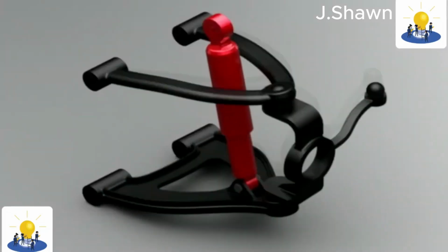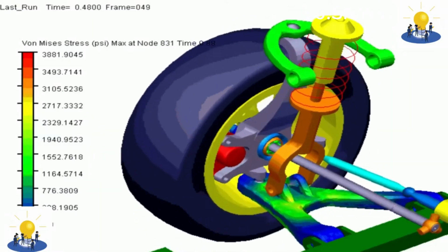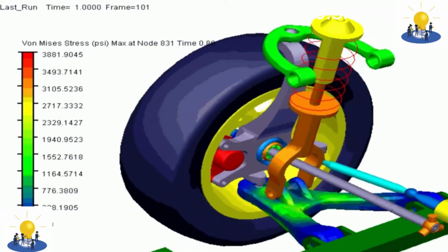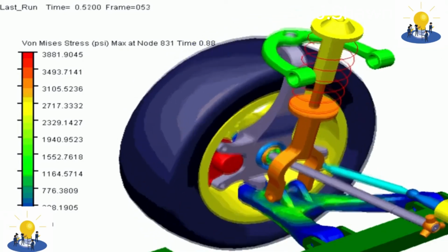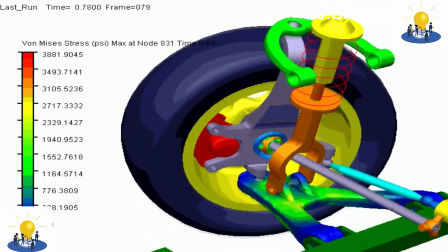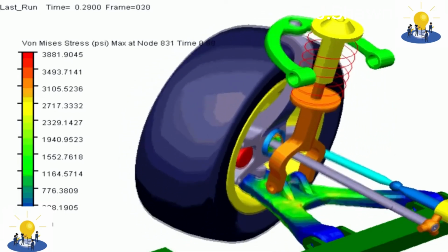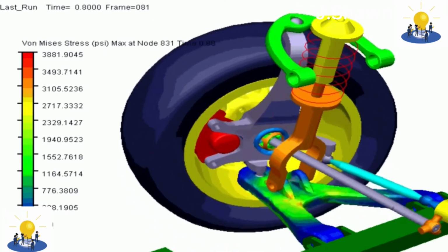In elevation view, the suspension is a 4-bar link, and it is easy to work out the camber gain, C-camber angle, and other parameters for a given set of bushing or ball joint locations. The various bushings or ball joints do not have to be on horizontal axes parallel to the vehicle's center line. If they are set at an angle, then anti-dive and anti-squat geometry can be dialed in.